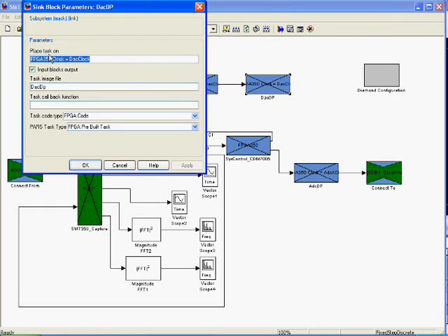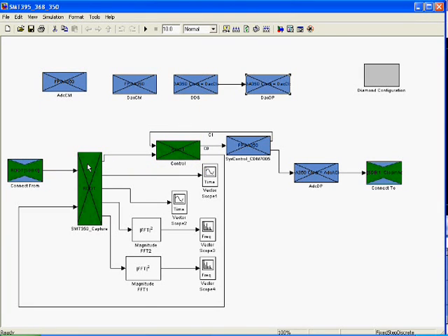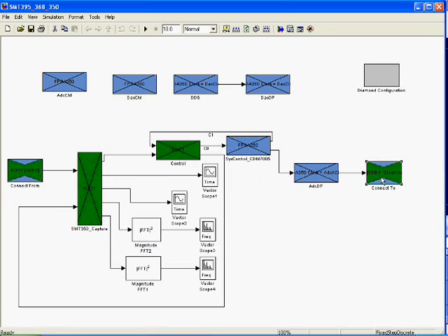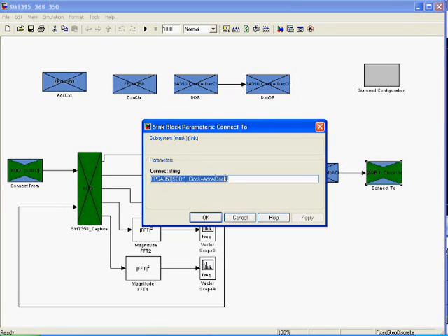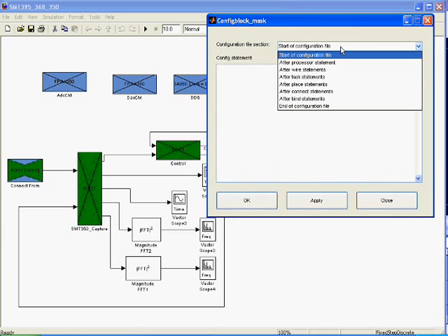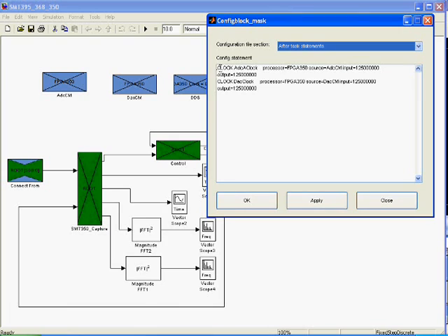As shown in the video, the DDS and DAC-DP FPGA pre-built tasks are driven by the DAC clock, and the ADC-DP high-speed channel is driven by the ADC clock. The ADC and DAC clocks are described in the Diamond configuration block as shown. For more information on clock description, please read the Diamond User Guide.